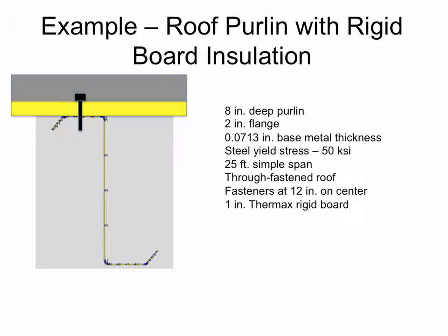Yeah, you've got an additional sponge in there. Stiffness of the board, probably not much, because the local buckling is going to be happening here, probably. So distortional buckling, is that going to be affected? Yeah, it's definitely going to be affected, and it's most likely going to be suppressed most of the way.